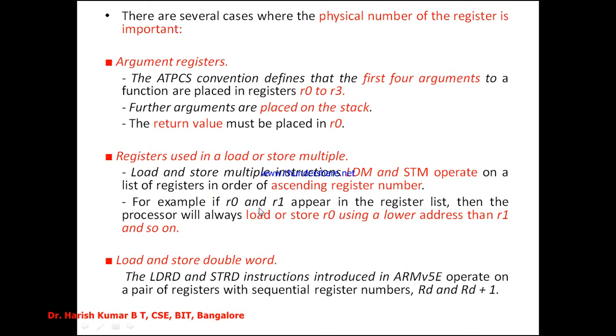Say, for example, I have registers R0 and R1 appearing in the register list for LDM and STM. The processor will always load or store R0 using the lower address. So for a load instruction, register R0 will be loaded with the data present at the lower address, and R1 will be loaded with the value present at the higher address.